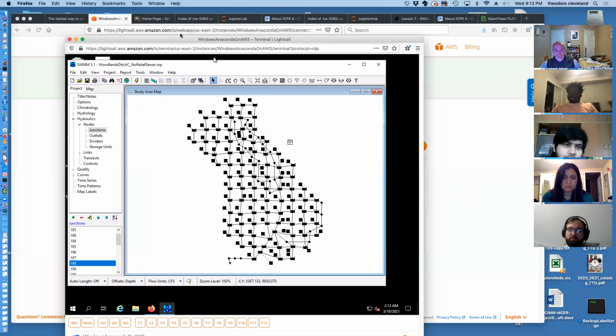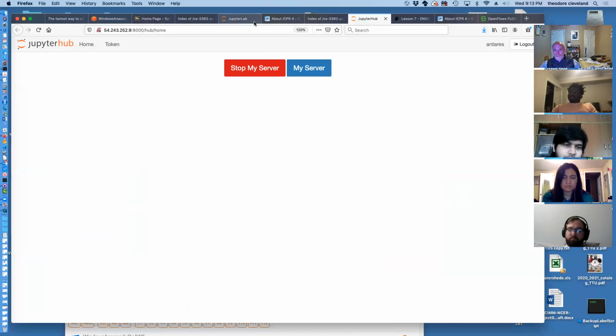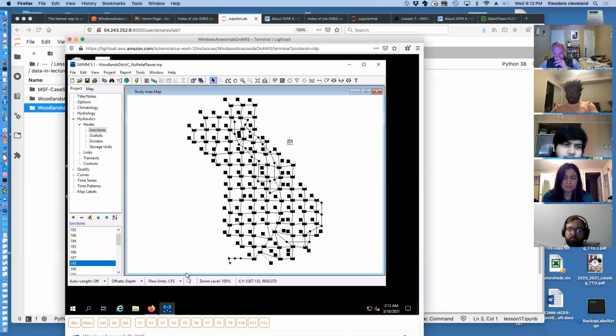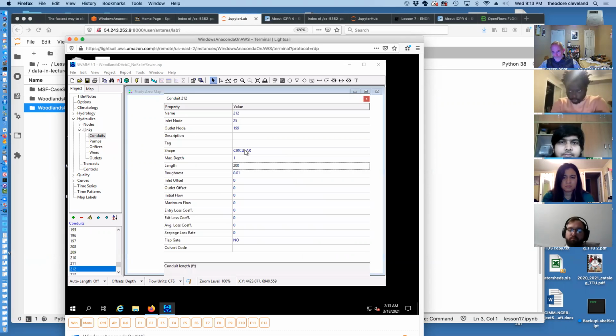So this model actually has all the pieces in my picture show. Those pipes are conceptualized in this fashion in locations where there's a surface link and a subsurface link. And you notice the model actually did a fairly clever trick and intentionally moved the pipes off of the grid system axis so that they could find them in the future when the client asks questions about them, and then connected the storage unit into the subsurface with a 1-foot lateral connection.